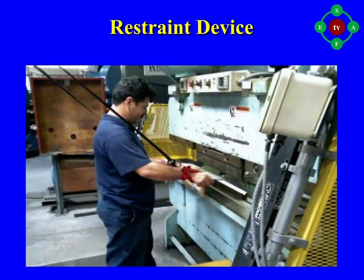Restraint device. Use cables or straps attached to the operator's hands and a fixed point. They must be adjusted to let the operator's hands travel within a predetermined safe area. Hand feeding tools are often necessary if the operation involves placing material into the danger area.